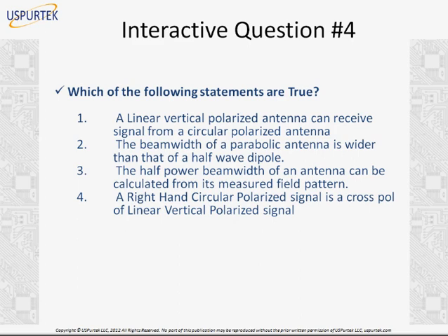Well, there is a question, then why use linear? Well, linear because, of course, it's a matter of implementation. Of course, there are benefits for having circularly polarized antennas, but that will add to the cost of your handset, the cost of your base station. To keep things more practical and commercially deployed, we use linear antennas mostly. But definitely, you have a good point here.